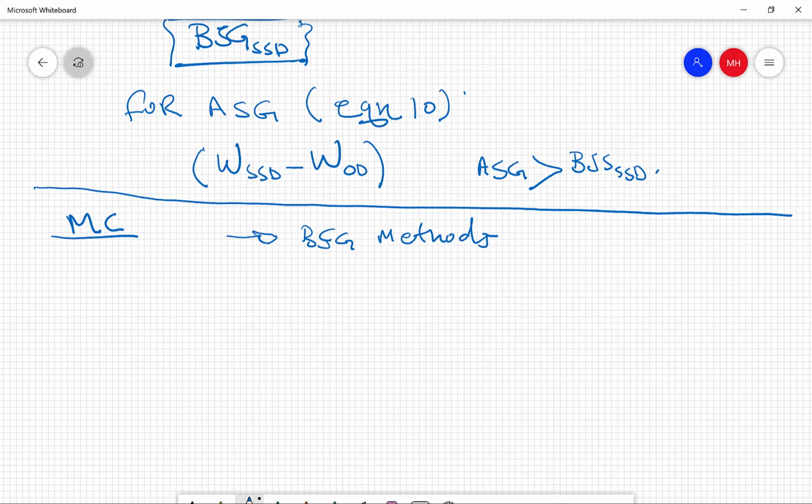All right, the procedure for determining the surface moisture in fine aggregate is given in ASTM C70. But the principle behind this method can be used to determine the effective absorption or surface moisture of both fine and coarse aggregates.